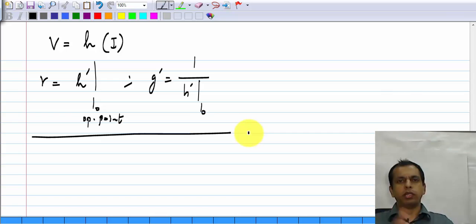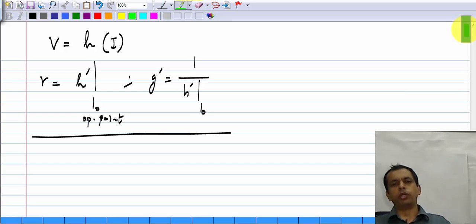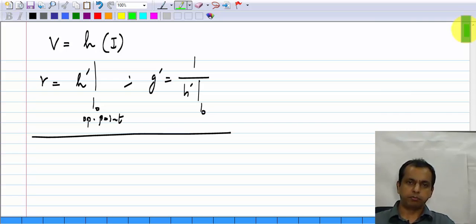So, every nonlinear element can be approximated by a linear element. Now, you see why this method is easier. We do not even need to write the nonlinear equations of the original circuit. You have to do it for calculating the operating point, but from that point onwards for increments, all you have to do is look at each element and replace it by its incremental equivalent.